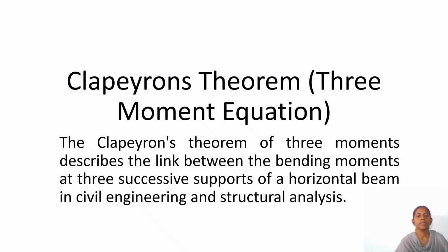In this video lecture, we are going to see the theorem of three-moment equation to solve indeterminate beams, otherwise called Clapeyron's theorem. This topic is included in unit 1 of structural analysis. This method is used to analyze indeterminate beams having consecutive spans and supports. Clapeyron's theorem of three moments describes the link between the bending moments at three successive supports of a horizontal beam in civil engineering and structural engineering.